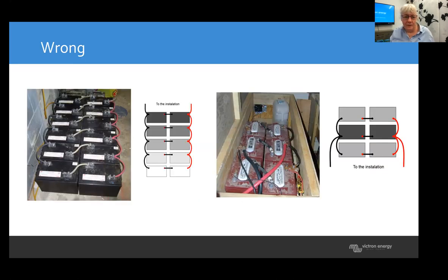Yeah, so again, from the internet, wrong things. Here they connected in the middle. They tried their best, but still it's not ideal. Here they connect on this side. So yeah, all the other batteries... It's actually wasteful for your batteries. It's breaking one and not using the full potential of your whole entire bank. It's stupidity. And the battery is quite often the most expensive part of a system, and that's a cost that repeats all over again. It's a consumable. So a lot of the money of a system goes into the battery. So why not do a proper job?